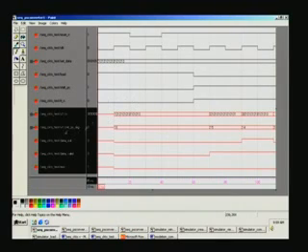There's also a counter which will keep track of the number of bits sent over the serial channel, and this we start with 16 here, and then it starts decrementing every time a bit has been sent, and the first bit that is being sent here is, say 1010 becomes 010, that means this has been right shifted, and so the very first bit on the LSB will go out as data out. That's what you have it here.